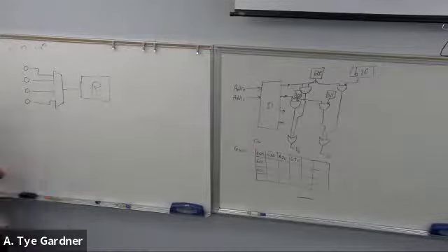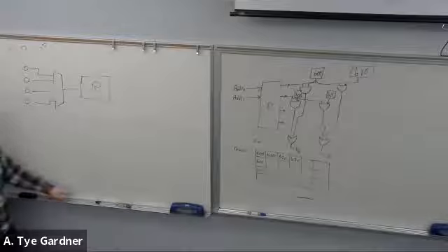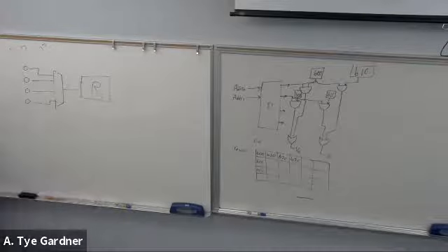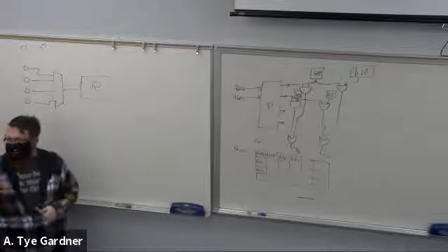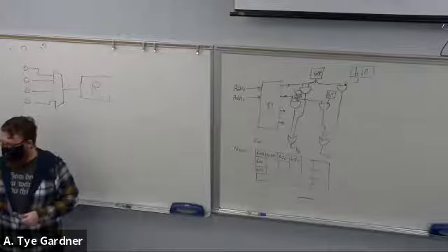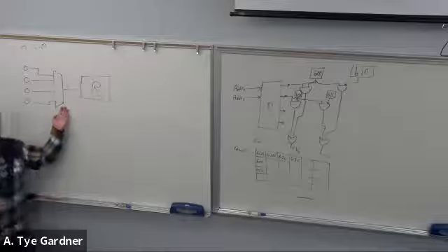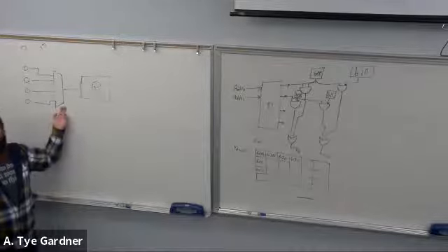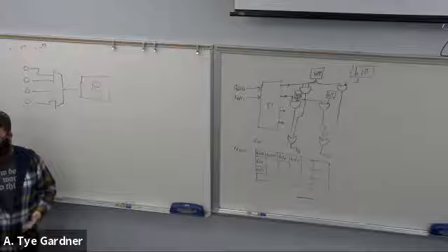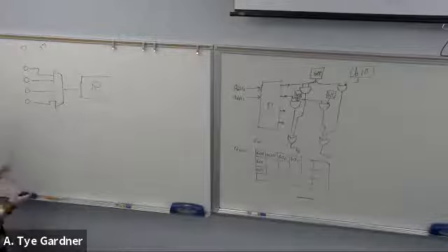But gray code actually turns out to be the right way, so to speak, of doing this, because using binary has an issue. So we talked before about it takes work to change a gate, right? These have gates in them. And I said I wanted 1,000 channels, right? So let's say I have, or thousands of channels. Let's say I have 8 bits of mux select.